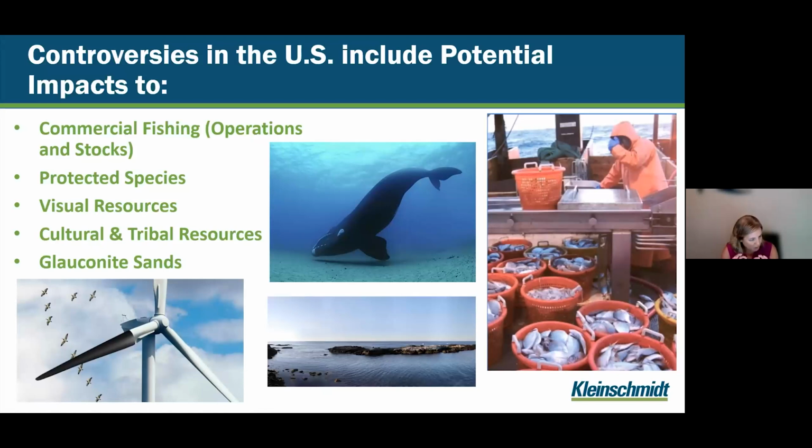And then one just a little unique one to put in there for the project that I'm working on are the presence of glauconite sands, which I actually had never heard that word before a few months ago. But you've got this lease area now that the developer has paid to develop, and they go out and do the surveys and have identified that there are some subsurface sands that will result in pile refusal. So while their intention is to go out and pile drive these monopiles as part of the wind farm, the sand won't let them. So this is now kind of a new thing that has come up and that we're trying to figure out how to deal with.